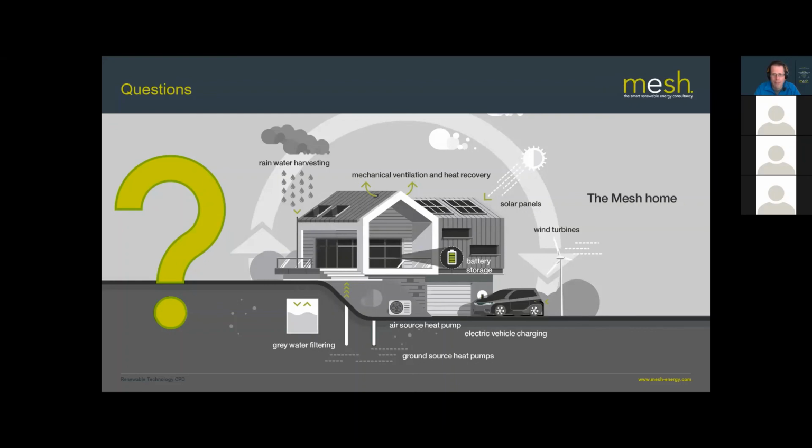And that means you can physically fit more panels onto the same area of roof because you don't get any issues with inter-row shading. So if you remember, I talked about inter-row shading where the row of panels in front then shades the row behind because of how the sun comes down onto the roof. So you get a lower output per panel from an east-west split, but you may get a higher total output on a flat roof because you physically can fit more panels on.